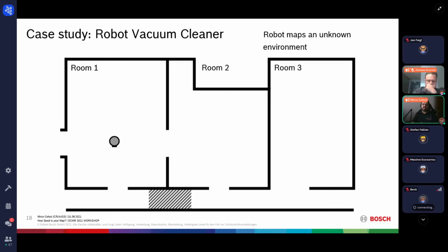Our SLAM system is decoupled from the navigation subsystem. Then the motion controller decides where to go. It's not something that SLAM should handle. Once the robot is turned on, the first thing it needs to do is some initialization of the system, loading of configuration parameters, maps, some kind of calibration, and once it's initialized, it starts its mapping session.